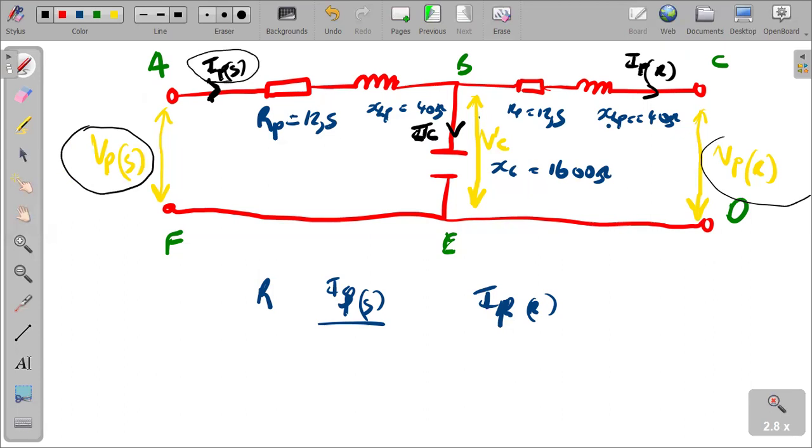Right. I want to explain first. So the diagram is good. No wonder I was saying, even if the question had not asked to draw it, it was good to draw it so that you can guide yourself on what is happening. We want IPS. And IPS, remember, even if you say IS, you are still fine, no problem. But don't forget we are dealing with phase values, right? So IPS is equal to IPR plus IC. It means these are the two that need to be calculated. Why? Because according to Kirchhoff's first law, current entering a junction is equal to current leaving the junction. So it means this is true, right?